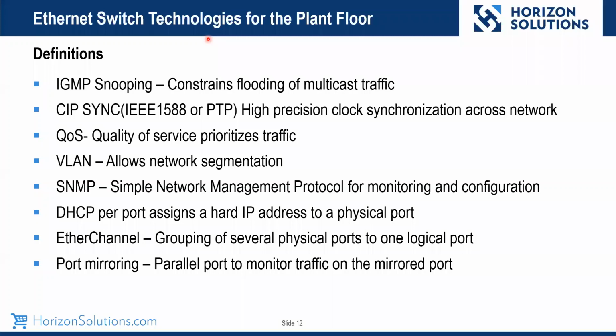CIP Sync, IEEE 1588, precision time protocol, all the same thing. That's how high precision clock synchronization across the network. And actually, with today's switches and this protocol, we could do a plus or minus 100 nanosecond synchronization. So if you're doing motion, sequence of events, timestamp and logging for pharmaceuticals, this is a protocol that you want to have included in your switches.